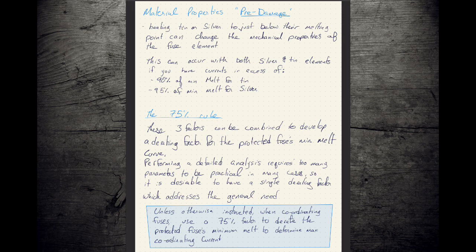So if you think about steel, right? You can harden steel, or you can anneal it, a process called annealing, which makes it really, really soft. The way you anneal steel is you heat it up until it's almost about to melt, and then you cool it down nice and slow. And if you do that, you could take let's say a knife blade or a file. A file is a great example, right? So a metal cutting file or a wood rasp.